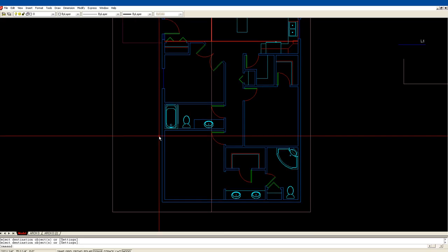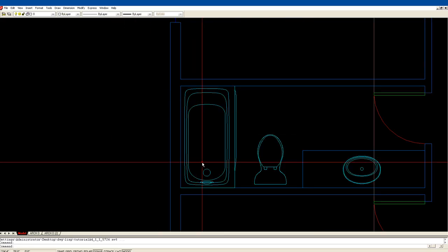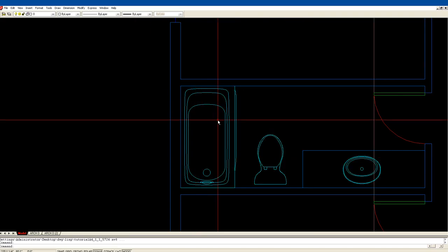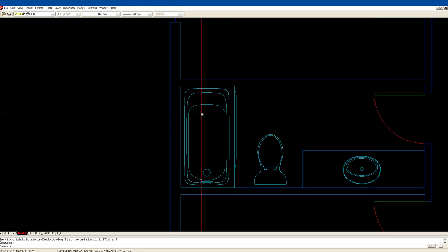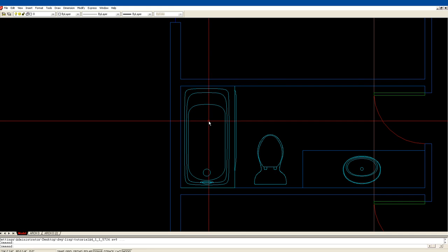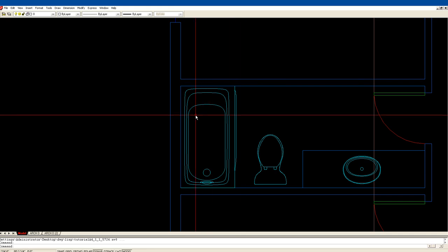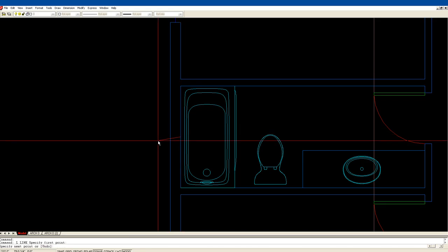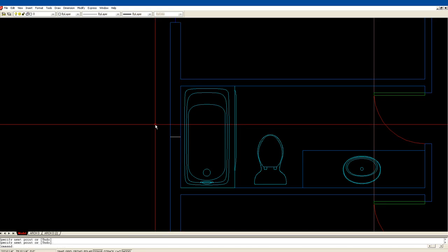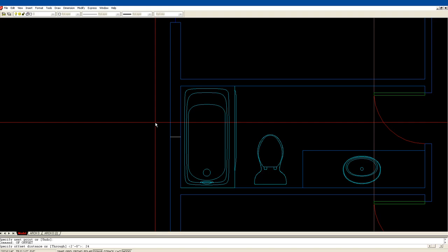Now here, he does want a window, but typically we'll have a shower in this tub. It'll be tiled, or it'll have a tub surround, so that you can use it as a shower as well. And they'll just draw a curtain or a glass door, slide back and forth. So this window, we'll put it in the center of the wall. We will make it 4 feet wide, so offset 24.